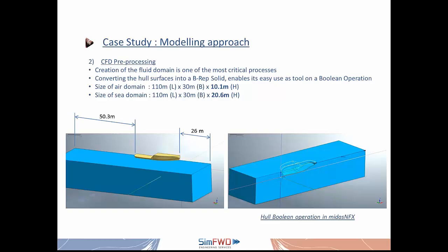So we have started with creating our fluid domain, which is a critical process for starting the hydrodynamic analysis in this part. We have used the modeling tab of Midas NFX, and we have created a solid box where we have given the appropriate dimensions according to our hydrodynamic needs. So we have an air domain, and we have a sea domain as well, where we have split them at the design water line.